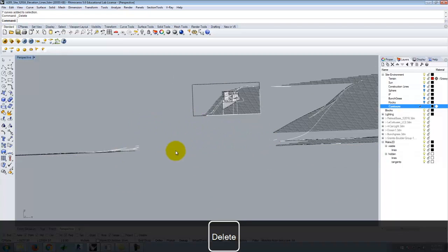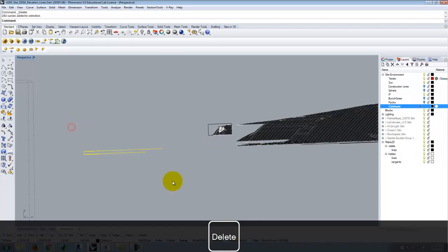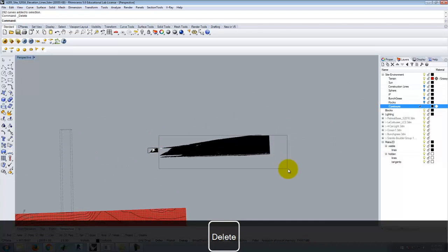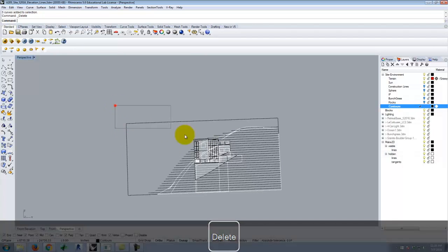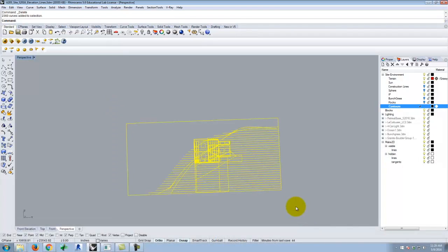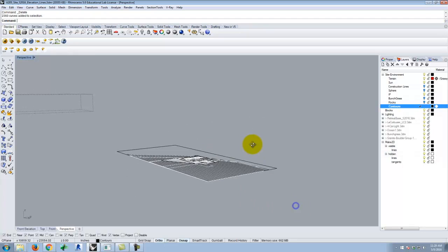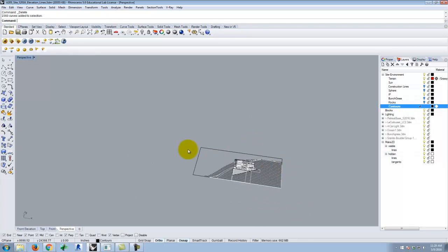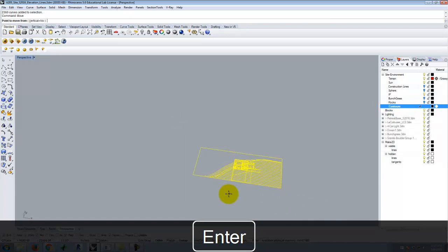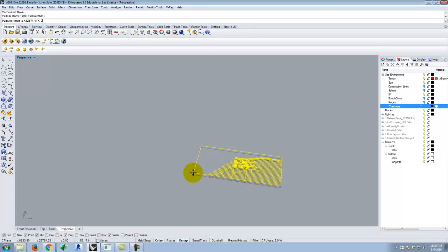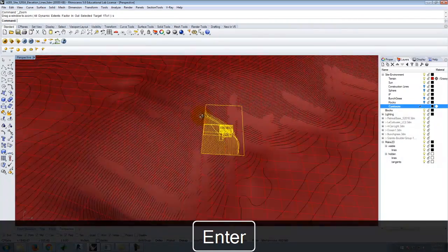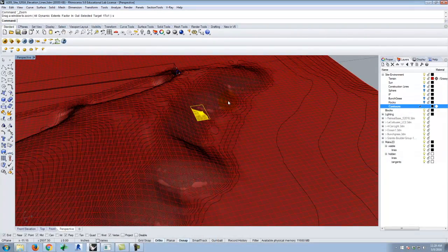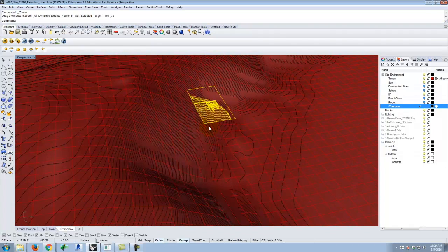Get rid of all this, because this is far beyond the scope of what I'm going to show or need. We'll clean that up, and now I end up with just this, which represents the ultimate drawing that I'm going to use. And again, it's flat. I'll take this, and I'm going to move it from this point to 0, 0, 0, so that it's at the origin. I'll zoom selected so that I can see it. Obviously, it's floating out there in space because of the rest of my model. It doesn't matter. I just need this to be at 0, 0 for when I do the export.